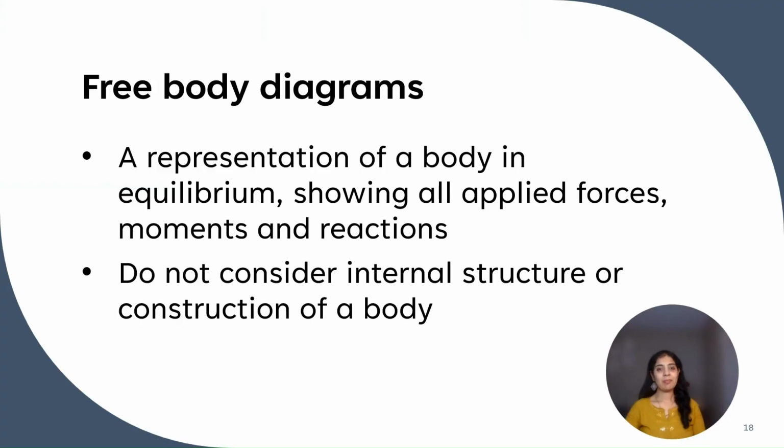Free body diagram. You have heard this word a lot. So what is a free body diagram? It is a representation of a body in equilibrium, showing all applied forces, moments, and reactions. So, while drawing a free body diagram, do not consider the internal structure or construction of a body.